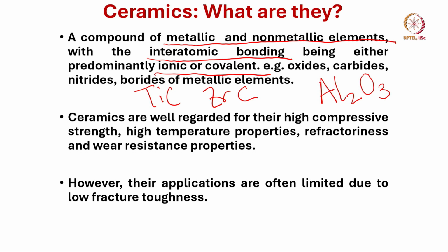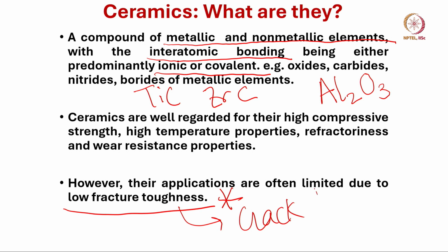That is what is important for refractoriness and wear resistance properties. The key point is that broad spectrum engineering applications of ceramics are often restricted by low fracture toughness. I remind you that fracture toughness is essentially a measure of crack growth resistance.